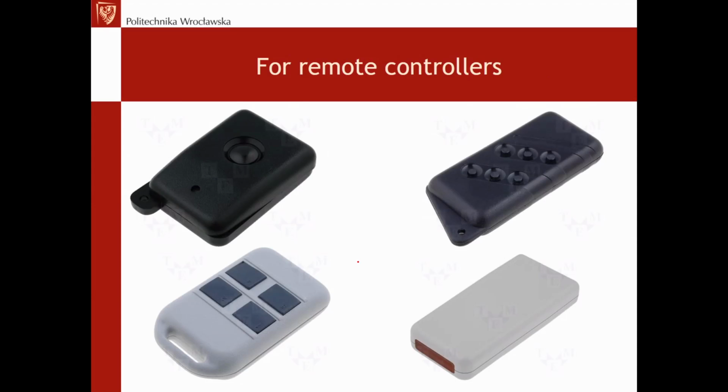What's the advantage of this method with the use of the 3D printer and the dedicated case? The advantage is that you can then design the case much later in the design process, because you don't need to exactly shape it already between the schematic and the PCB design.